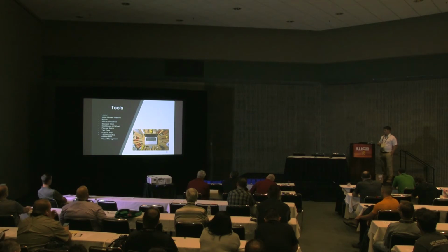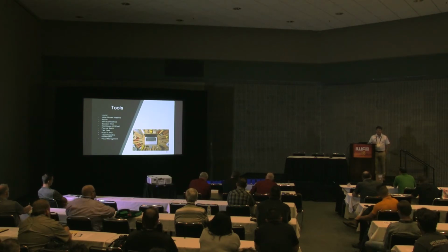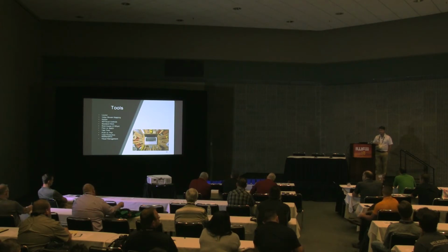Kaizen, continuous improvement bursts, high energy, high focused operation to improve an individual workflow, doing 5S, single piece flow, organizing the work cell for both ergonomics and productivity, as well as safety. 5S and visual controls. Does anyone use shadow boarding? Organize your tools. Only have what you need, not every single tool you've ever used in your toolbox, right? So you spend time looking for it.